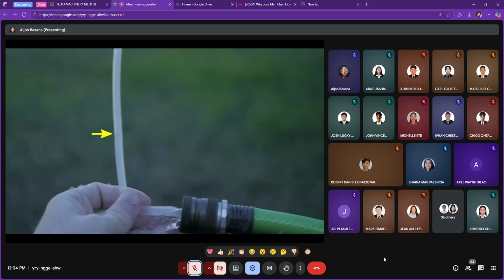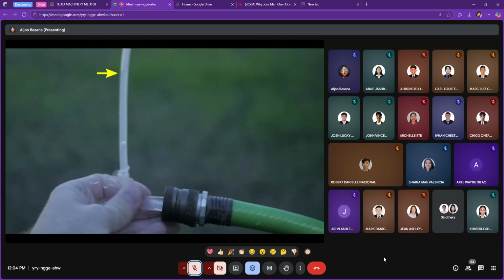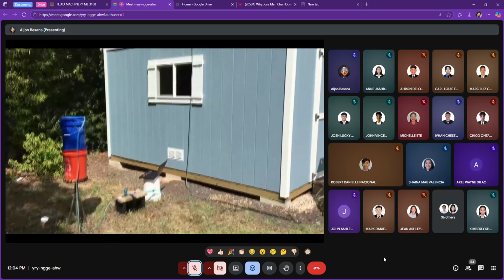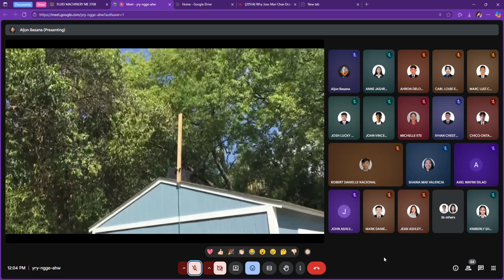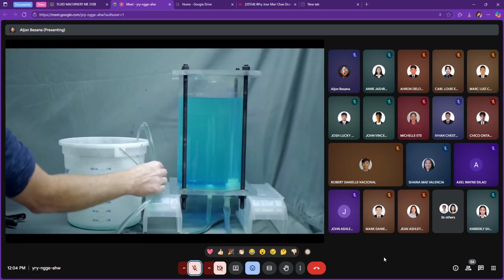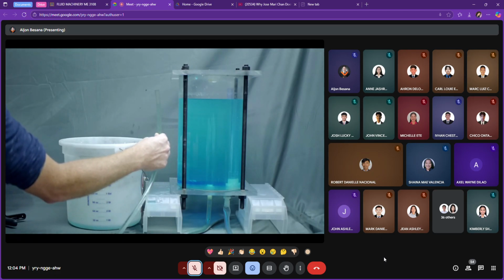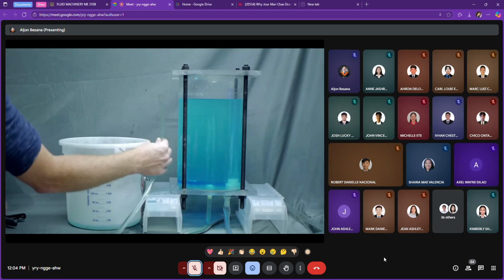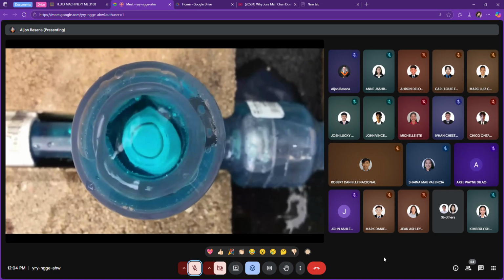That's a lot of background, but it's important in understanding the function of a ram pump, because without an external source of power, even though you can go from one type of energy to another, you can't get more energy out than you had at the start. For example, I can convert a static column of water to one with some velocity, but I'm never going to get the fluid to a higher elevation than where it started, with one exception. An exception that the hydraulic ram pump takes advantage of beautifully.